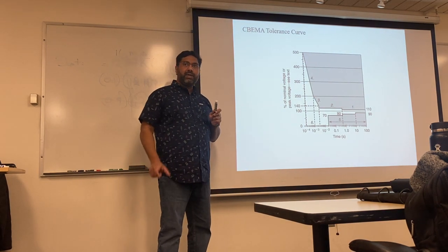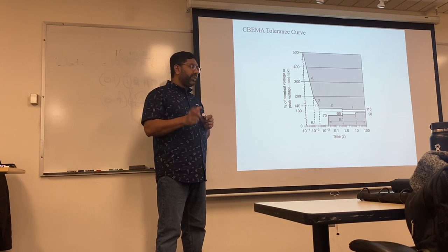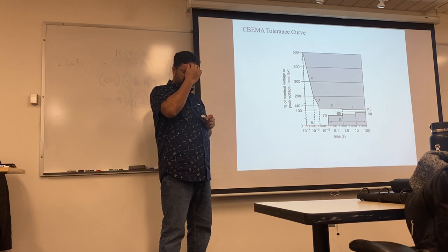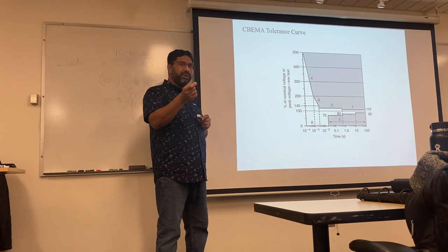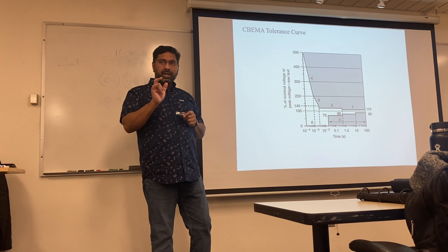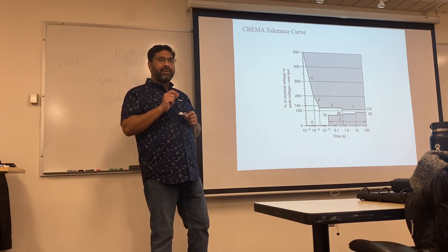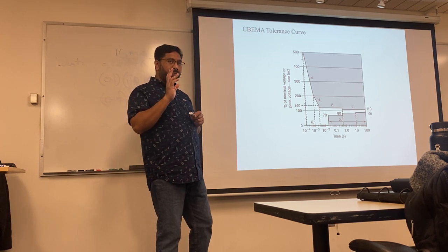When we were doing the calculation for the breaker, on the off chance, I believe we spec'd 40 ampere, no, it was 39.1 and I picked a 40 ampere breaker. But there is a chance that you give 40 amps and the breaker doesn't open. It depends.